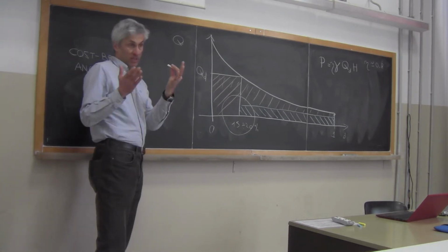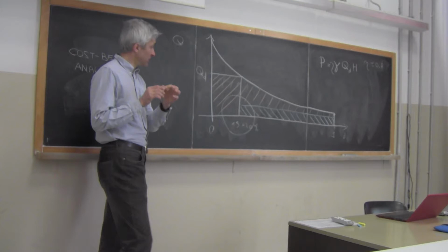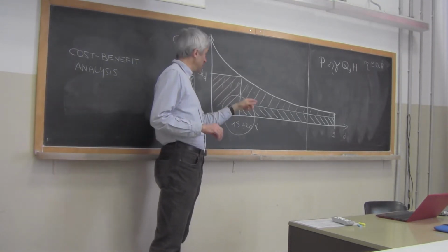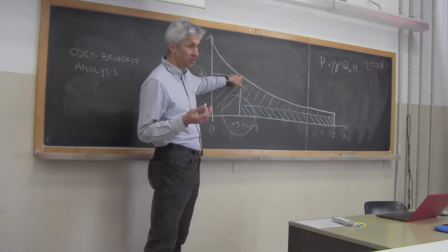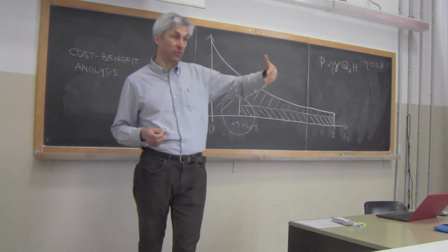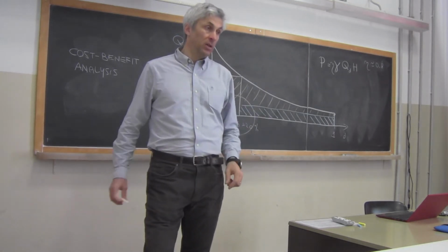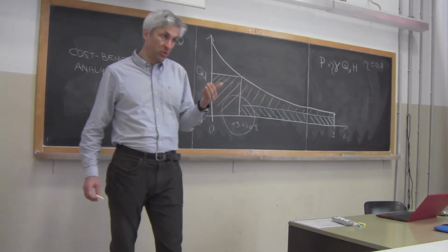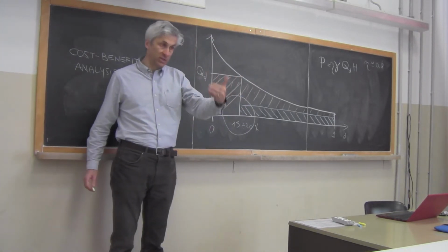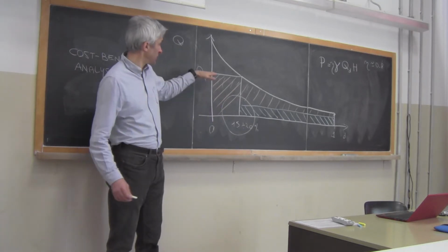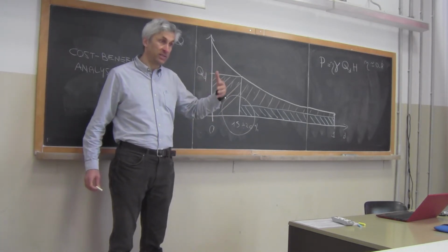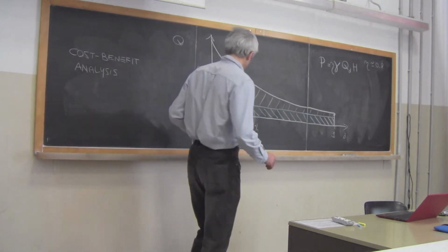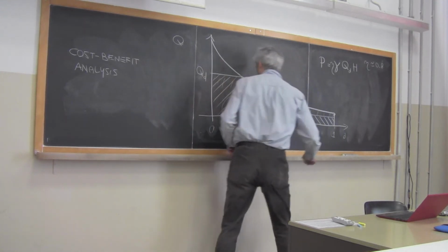Because, you understand why? I cannot stop my environmental flow at this stage, here. Because I still don't have an excess river flow with respect to the design flow that compensates for the environmental flow. When there is full compensation, I mean when I am sure that the environmental flow is released downstream, even if I take the max flow, and it's released because there is an excess flow with respect to the max flow. Okay? The answer is not difficult.